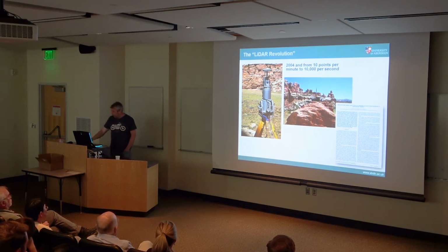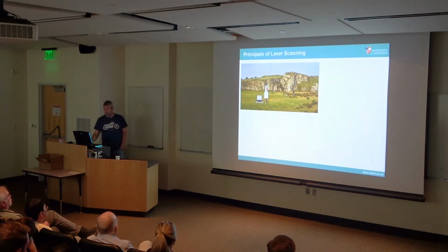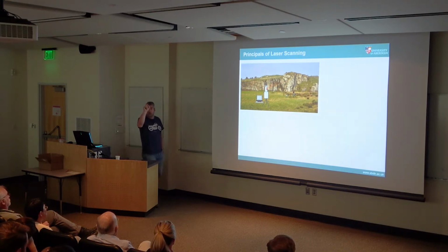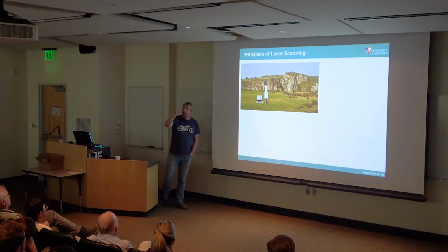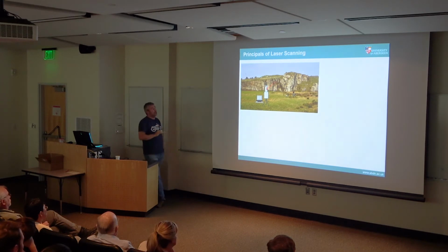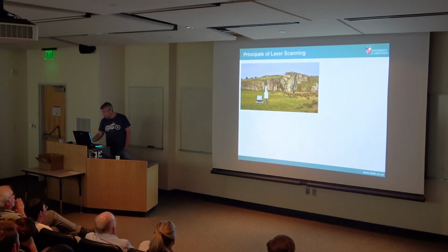And the principle of LiDAR, if you're not familiar with it, is it's basically you have a static unit that sits still. It knows where it is because it's got a GPS on it. It shoots a laser beam at the cliff. Each time it hits the cliff, it records the position of that point from the time of flight, and it records that position, and then it's all sort of combined together.